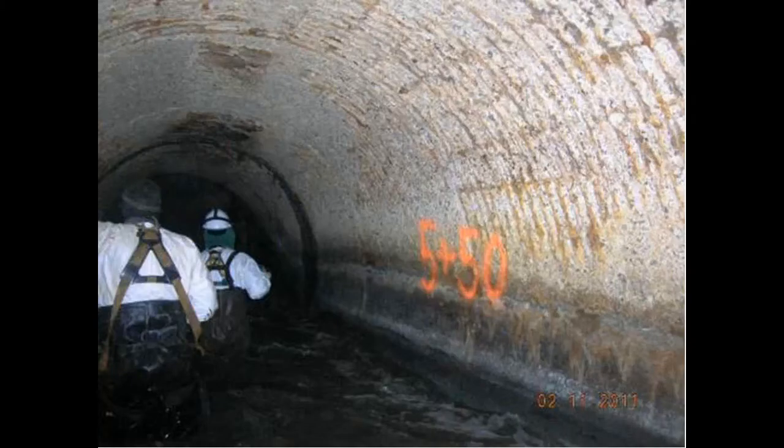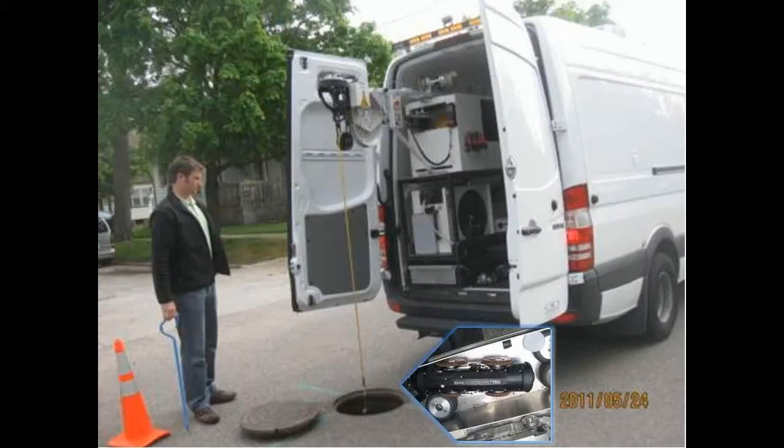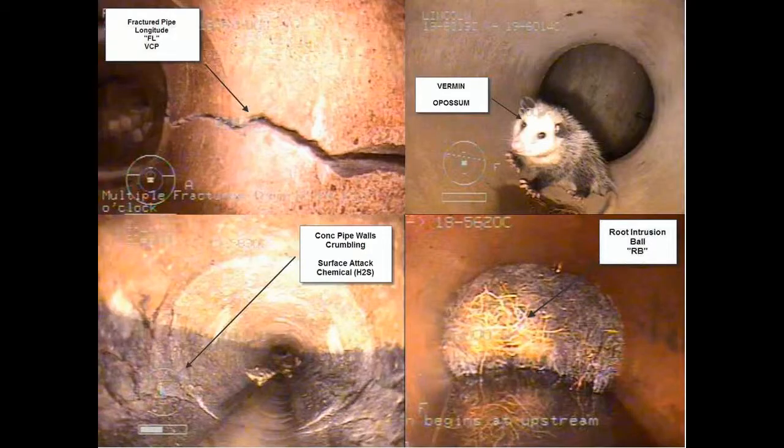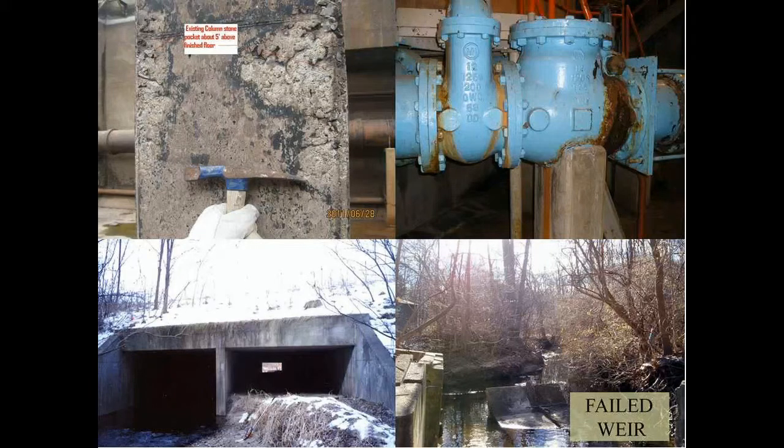Here's a picture of some condition assessment of a combined sewer. Televising, cleaning and televising are going to be eligible costs. Condition rating of your sewers using PACP ratings from the NASSCO system is eligible. You can see many sewers are going to find lots of ways to spend money. Also at facilities or in stormwater systems, physical inspections can aid in determining condition assessment of your assets.